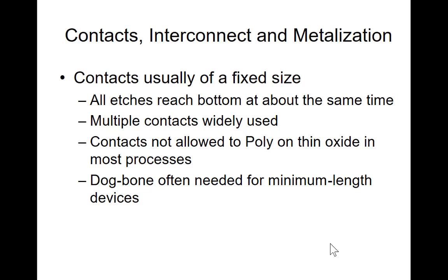So you can do these things, but many times, if you are doing minimum size transistors, your gate poly and the active overlap, and this overlapped area is your active transistor. So that's where your transistor is. The overlapped area is the most critical area that forms your transistor.